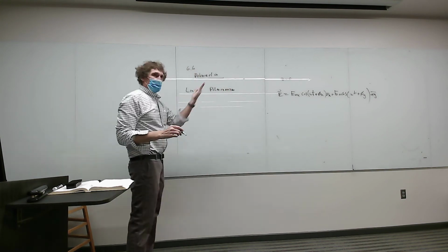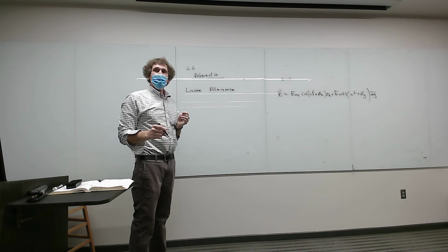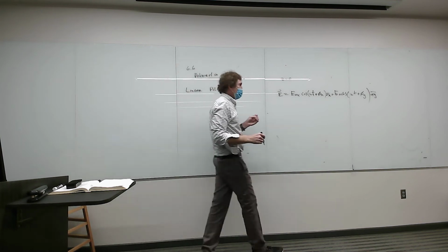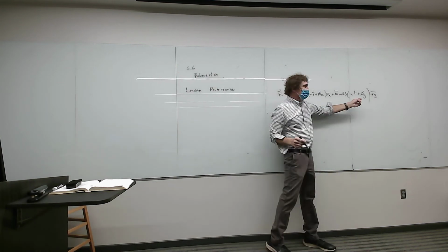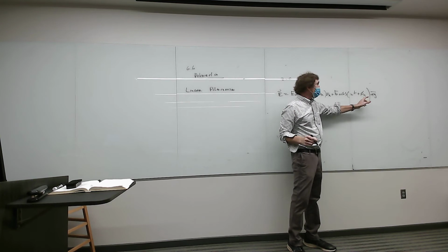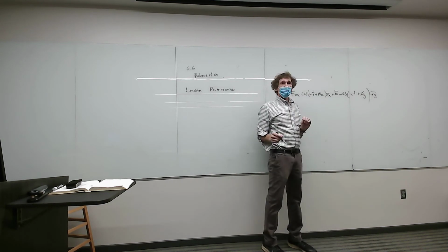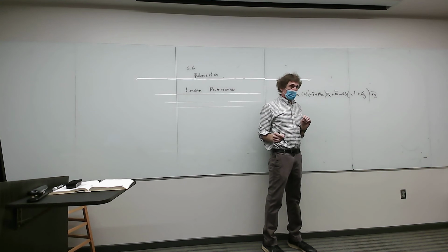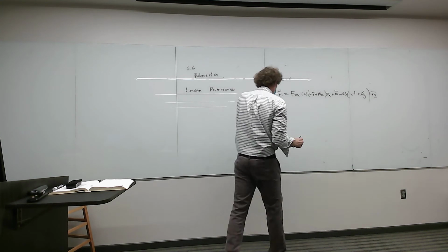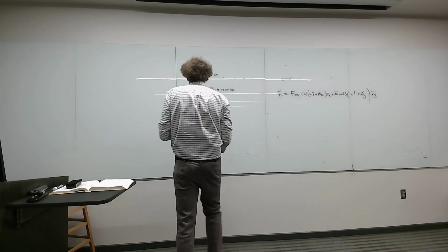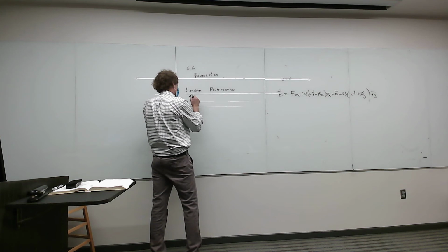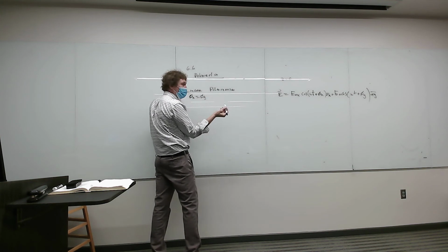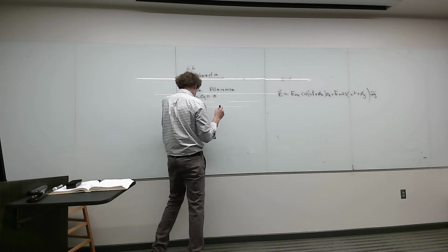So now, if you want linear polarization, linear is a straight line, right? For linear polarization, what you want is the phasing of this wave and this wave to be the same. So you make phi y and phi x the same. That's an easy way. There's more ways. Do you all see this? Now think about what happens if you make phi x and phi y the same. Here you make phi x equal to phi y. And for our purposes, let's make them equal to 0.